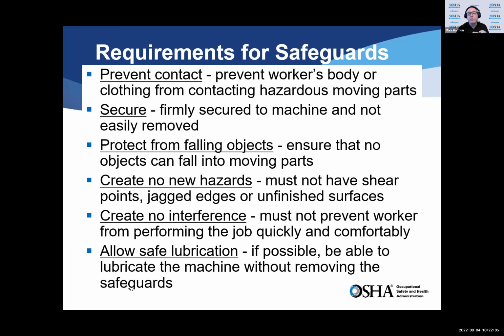Protection from falling objects. Make sure that there are no objects that can fall onto your moving parts. Again, this goes back to what we mentioned with the use of tools. Sometimes I walk by a machine and it's got some moving parts on it. It's got some nice looking guarding, but I look and there's an oil can here. There's a tool bag there. You don't want things like that to fall onto the machines. So storage is important. Keep things back.